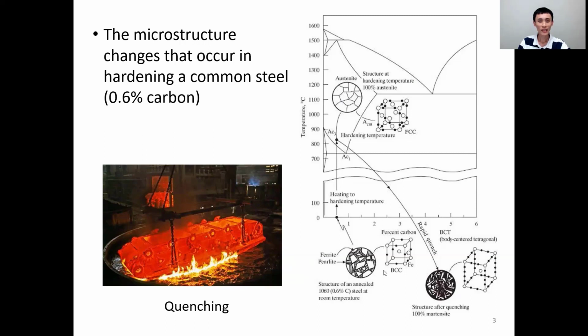into cold media. In this process, steel is originally in the structure of body-centered cubic. Then we heat it up into the austenite area. There are more carbon and iron in the cell, and the structure turns out to be face-centered cubic, which has more carbon and iron elements in the cubic.